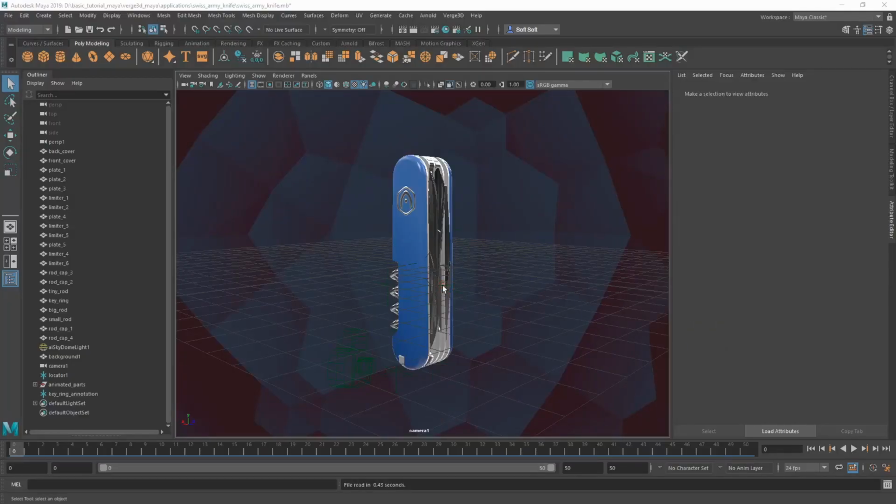Okay, now let's optimize the geometry to reduce the number of render calls. The thing is that each separate mesh requires certain processing before sending to the video card for rendering. So, if you have multiple meshes that share the same material, it makes sense to join them into one.